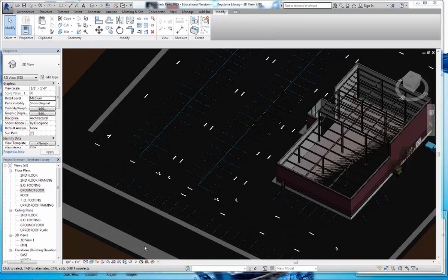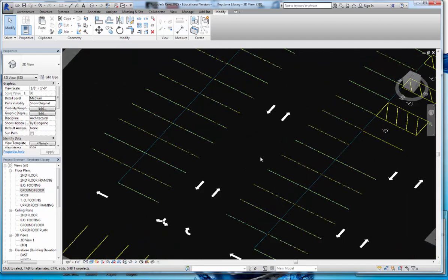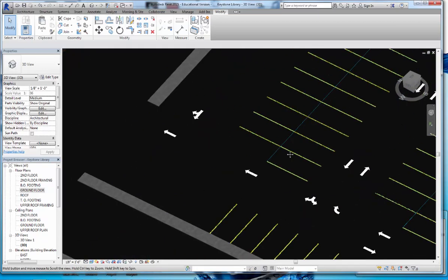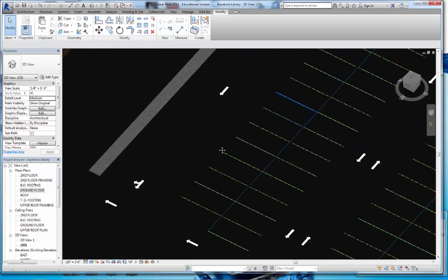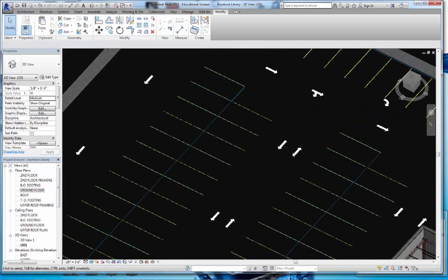I need to quickly mention also that for opposite or opposing parking spaces like this, where there's a space in between them, you need to make sure that for 2 directional traffic, you have at least 24 feet of space between the 2 lots. If it's one directional, you can have 12 feet, but for 2 directional, 24 feet, and we just use that as a rule to make sure that everything has enough space for at least 2 vehicles.